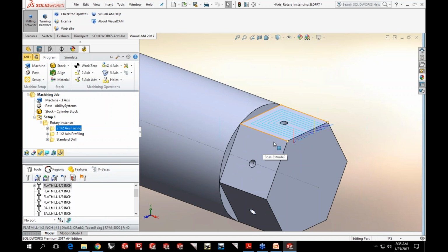So if we have an open pocket in here, the geometry, the feature I've selected in here is actually an open pocket. So I have three sides. So when we have an open pocket, selecting two-axis facing will ensure that the cutter will start from the side where it's open and will never go past, so it will treat the other three sides as side walls or part boundaries, so not to be machined away.